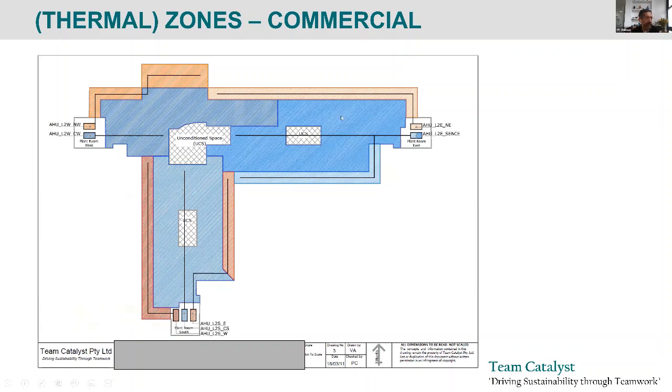So we have north facing up the page. Now, the north in Australia is exactly like the south in India. Okay, it's the sun-facing facade. So during the day, you're going to get sun all over that north facade. Okay. On the east, you're going to get sun in the morning. On the west, you're going to get sun in the afternoon. Now, if you think about it, if I had used the same air conditioning system to condition this entire zone, then somebody would be uncomfortable all the time, okay?